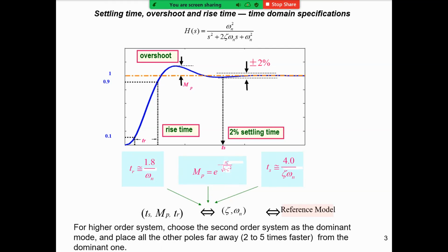And also you have to change the poles to make the output meet the performance requirements. So normally, from this one you get two poles, a second order system, but then it is a high order system. For example, for the mini project, you have to place the other four poles. You just place them far away from the dominant ones. Okay.